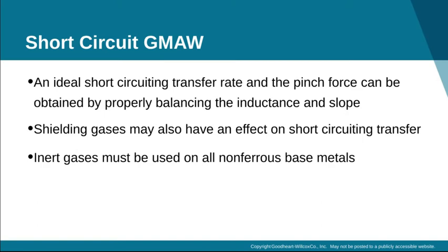Inert gases must be used on all non-ferrous base metals. So like you can't use CO2 on aluminum. It has to be totally inert, like just straight argon.